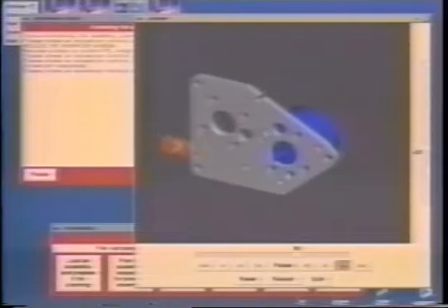Often, the first plan Archimedes chooses does not satisfy known process constraints. For example, in this product, the drive gears should be placed on the motors before assembly with the plate, and the mounting screws must fasten the motors to the plate immediately after the motors are placed.